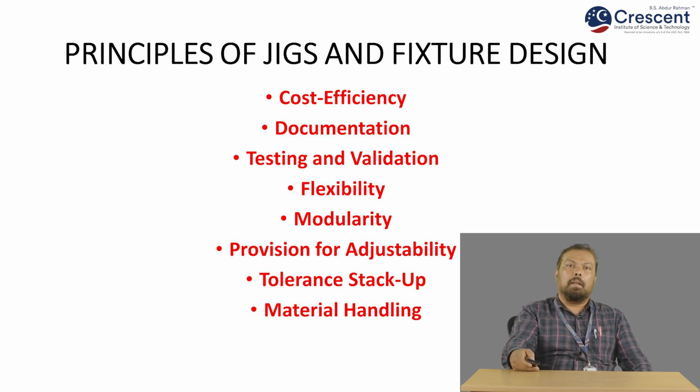Flexibility: when applicable, design jigs and fixtures to accommodate various workpiece sizes and shapes. This flexibility can improve the versatility of the tooling. Modularity: modular designs allow for easy adjustments and reconfiguration, which can be particularly useful in scenarios where product designs change frequently. Provision for adjustability: incorporate features that allow for easy adjustment of critical dimensions, especially in situations where workpieces